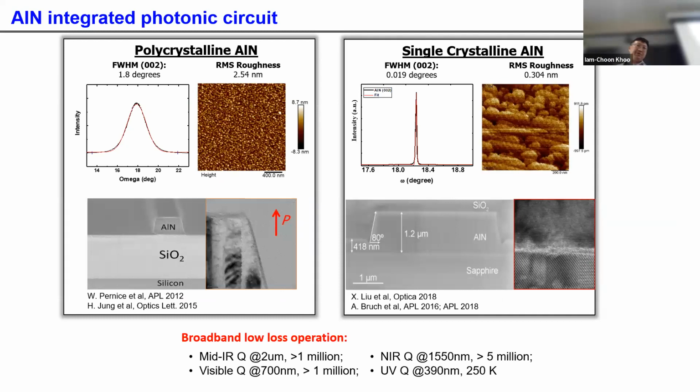So in our lab, we use 2 different types of aluminum nitride material. The first type really follows the MEMS process to deposit aluminum nitride on oxide. You can form a waveguide. The thermodynamics works so well that when you deposit aluminum nitride, even at a low temperature, it crystallizes and forms C-axis aligned domains that give you optical nonlinearity. And this domain is very small, only 20 nanometers. It does not introduce much scattering at visible light frequencies.